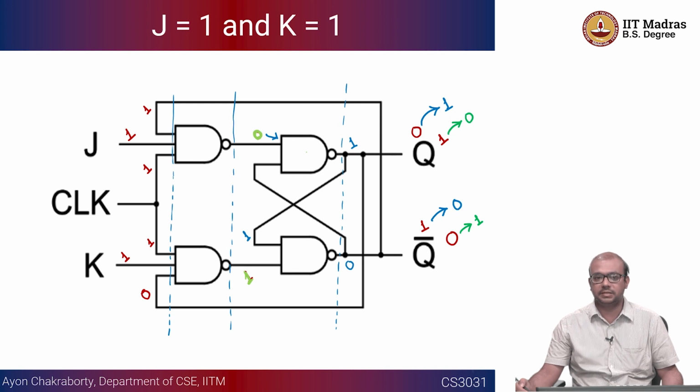In the previous three things, there was no toggle. There was either setting, resetting, or this is going to hold the memory element. Similarly, in case of D also, if you enable this, write enable is there. If you put D equal to 0, Q is going to be 0. If you put D equal to 1, Q is equal to 1. There is no mechanism in the flip-flop itself to toggle its states. For example, in a D flip-flop, I cannot do like if it was 0, I want to make it 1, or some kind of value inversion is not possible, right?